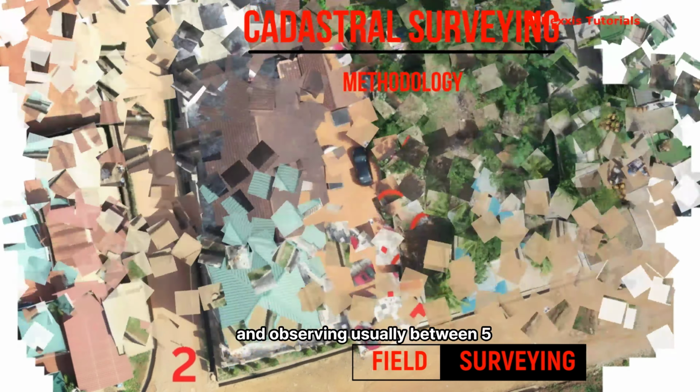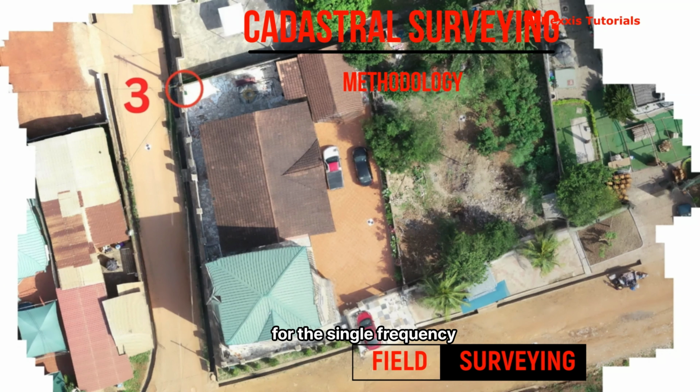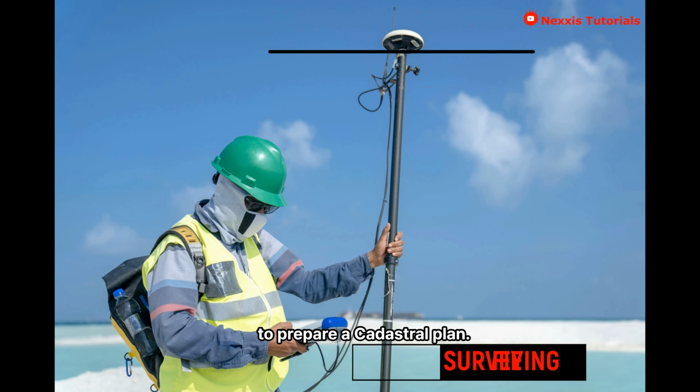So the licensed surveyor has the responsibility of physically accessing the property and observing usually between 5 to 10 minutes for the dual frequency GPSs and 10 to 20 minutes for the single frequency GPS. He observes on each of the corners of the property for that period of time to be able to obtain data to prepare a cadastral plan.